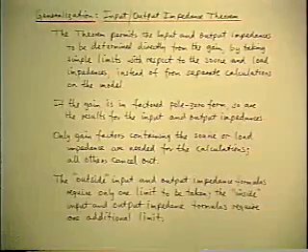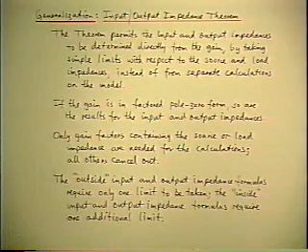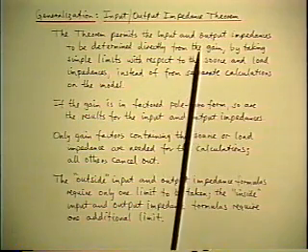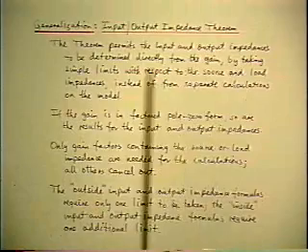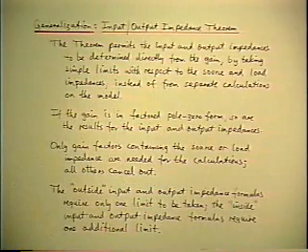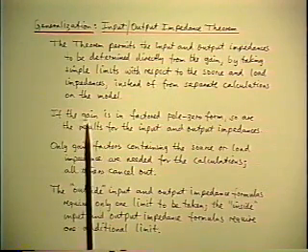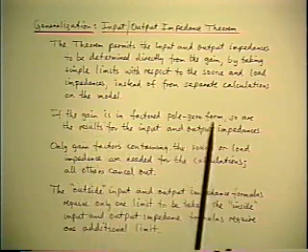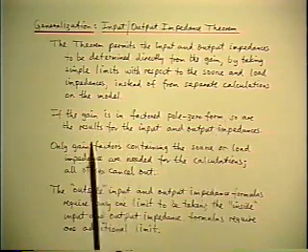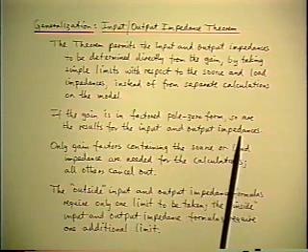Finally, to summarize the input-output impedance theorem, it permits those impedances to be determined directly from the gain by taking simple limits with respect to source and load impedances instead of going back to the circuit model and starting all over. You get some bonuses. If the gain is in fact in pole-zero form to start with, so are the results for the impedances automatically.